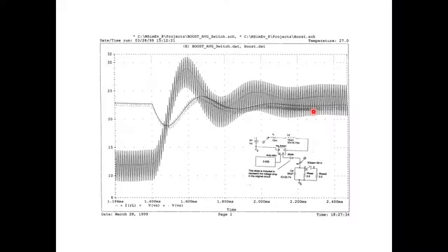This is a simulation of this exact circuit, for the same transient, except that I'm simulating this thing in that little box that says average model, okay? There is a diode there. That diode is just providing a constant drop, because keep in mind my approximate models didn't really include constant diode drops or anything like that. So that diode is not doing any switching. It's providing a constant DC offset.